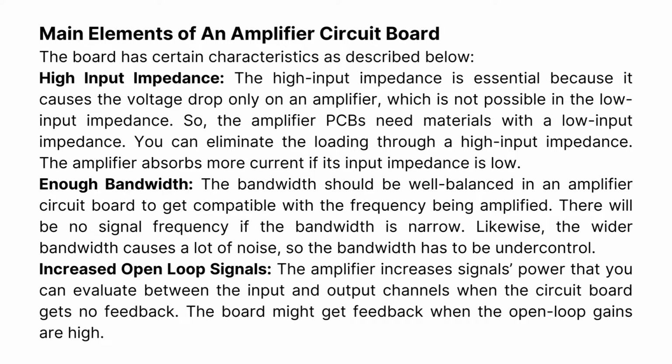Enough bandwidth. The bandwidth should be well balanced in an amplifier circuit board to be compatible with the frequency being amplified. There will be no signal frequency if the bandwidth is narrow. Likewise, the wider bandwidth causes a lot of noise, so the bandwidth has to be under control.